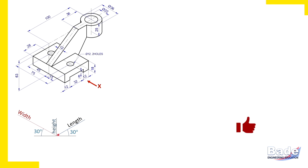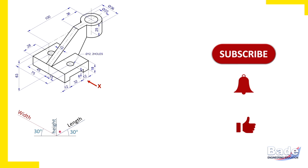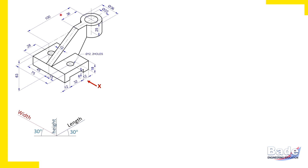Now we are able to identify overall length, width, and height. Focus on all dimensions which are parallel to the length axis. In this orientation, at top we can see from the extreme left end of the object up to the center of the cylinder, the dimension is given 100 mm, and the extreme right edge of the object is a curved edge.